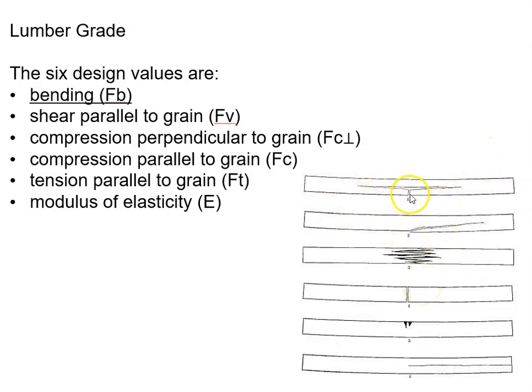We see tensile failures at the first two, right? They originate at the very bottom of the beam, so those would be tensile failures. We see these two are cracking all the way through. Here, something happened. This is on the compressive face of the timber, and here we see something coming right through the middle there, maybe a shear failure perhaps. Okay, so that is bending.